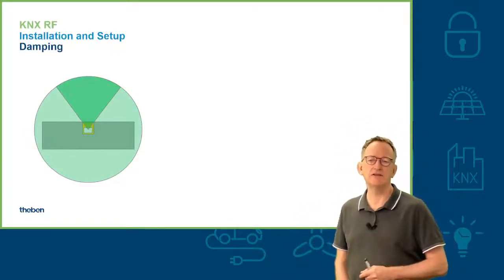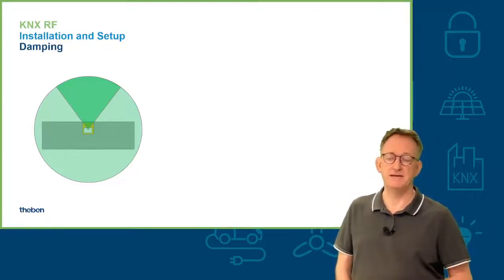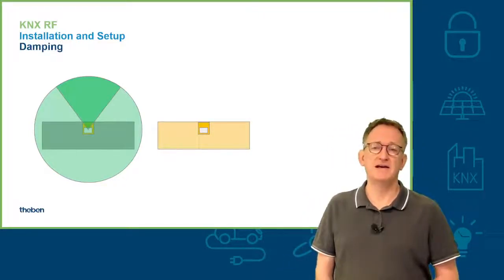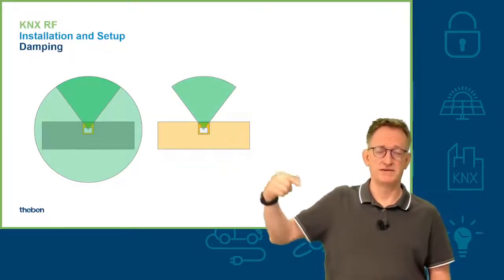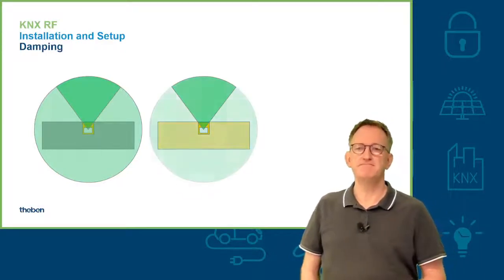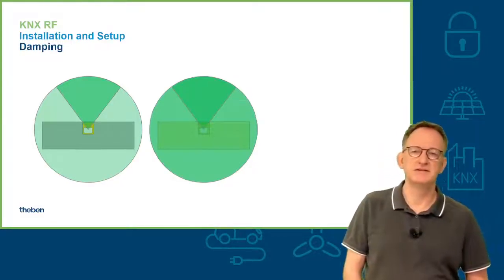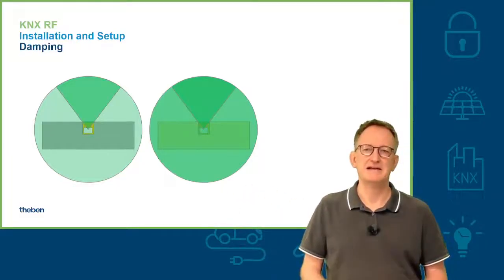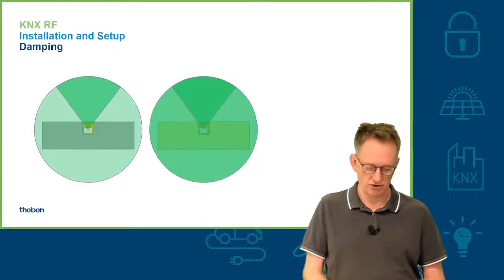It's not that good, it does not have that high quality, but you still might be able to communicate with devices. If you have a wooden wall, it's very similar with the devices in front of it, but wood has a lower damping factor. So it will be possible to send the signal better through the wall. Here we have much better conditions for RF communication.